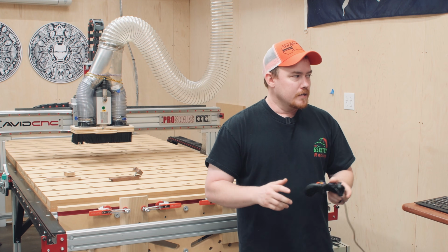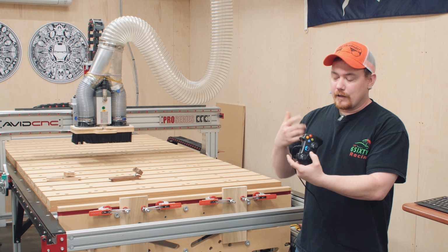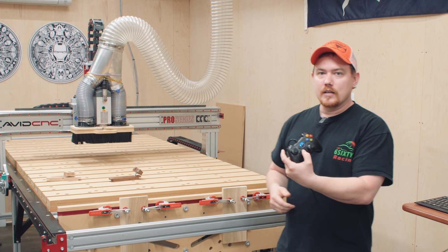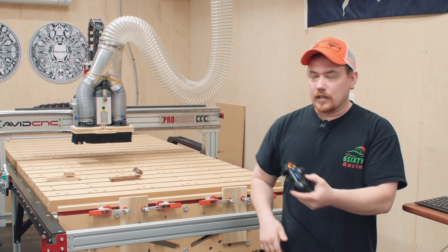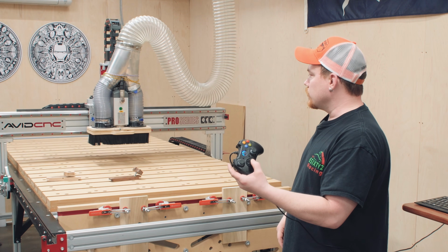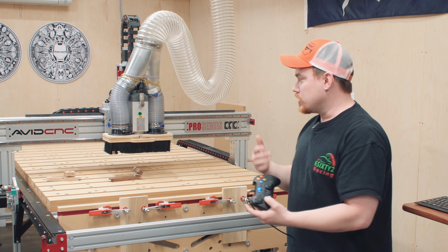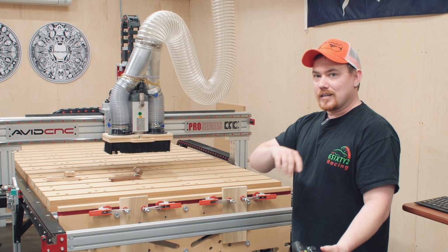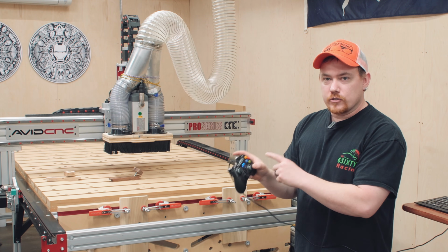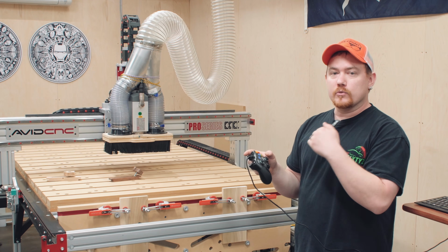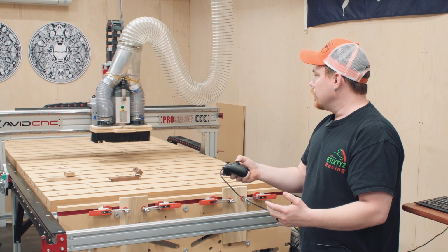So that's pretty cool. So in my setup for this Xbox controller, the left thumb has a directional pad, so you can use up, down, left, right, and that's mapped to the regular up, down, left, right of the keyboard. So that's your normal jog speed of 250 inches per minute. If I want it to move a little bit faster, it's on a completely different hand, so I don't accidentally bump into it when I don't want to, and that's the right joystick. Now this is all mapped to shift plus a direction, so it's much faster.